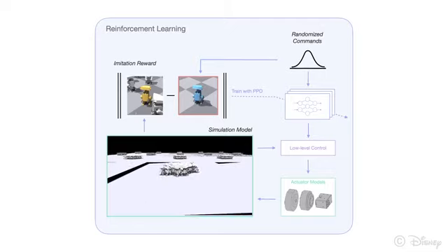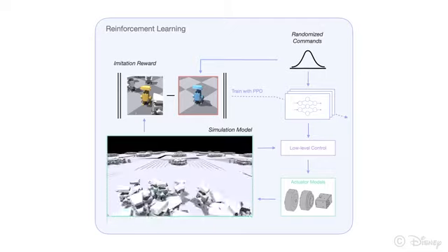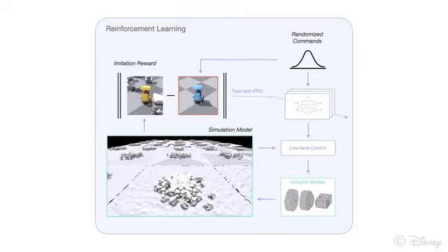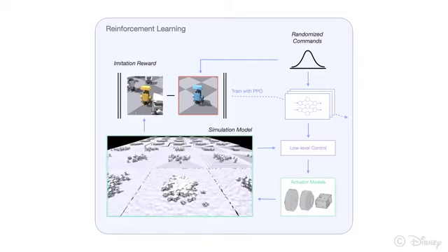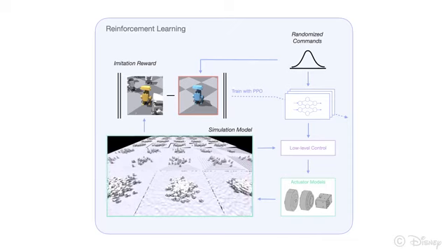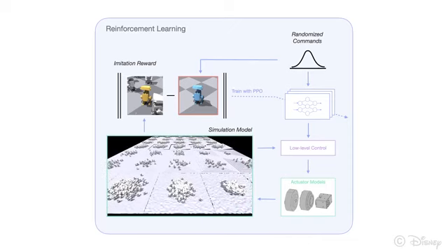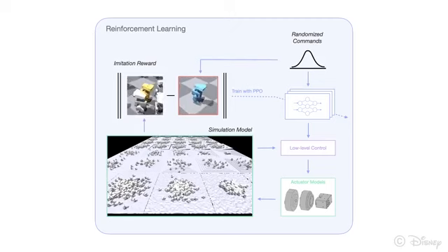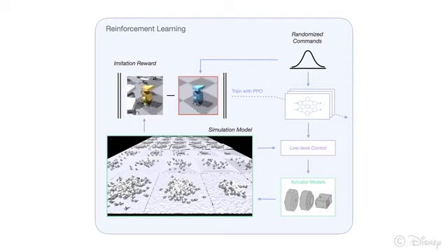We then use reinforcement learning to train control policies, asking for a simulated robot to balance stably and to track the motion of prescribed animations. The simulator is augmented with a low-level controller and actuator models, which we derive from real-world data, reducing the sim-to-real gap. The artist-specified reference motions are parameterized by command signals, such as walking velocity and robot pose, and are randomized during training. The policies are conditioned on those same commands and trained to imitate the corresponding reference motions using PPO.